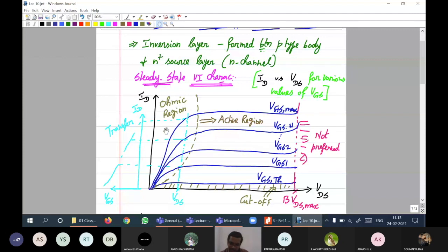So there will only be the drain source drop, VDS on state voltage drop. Only that will be present across the MOSFET in the ohmic region. Now that VDS on is given by total drain current ID multiplied by RDS on. RDS on would mean resistance of the drain source layer.